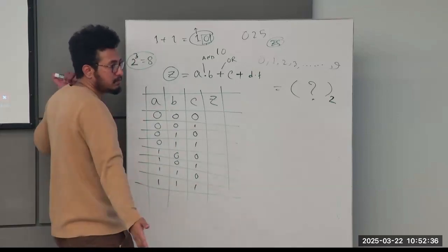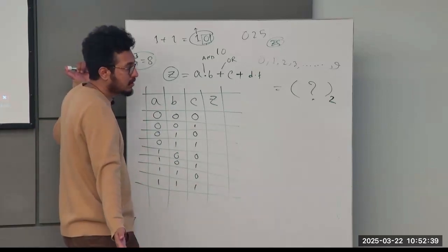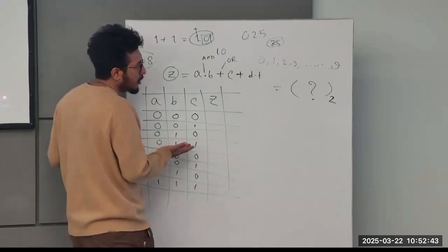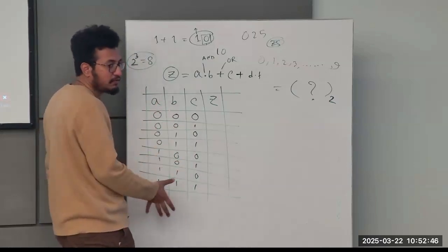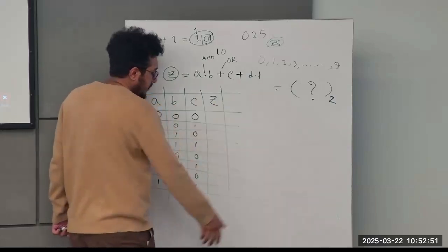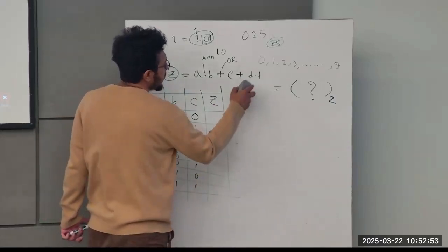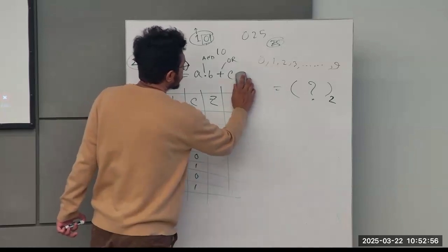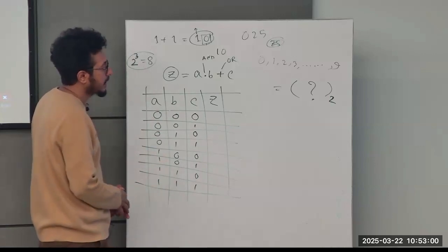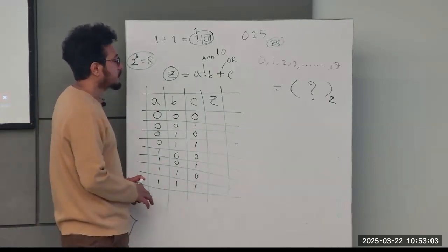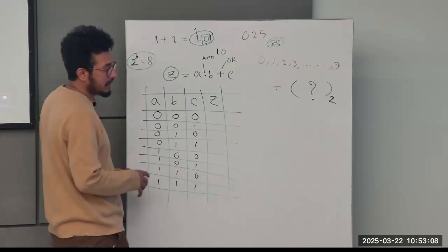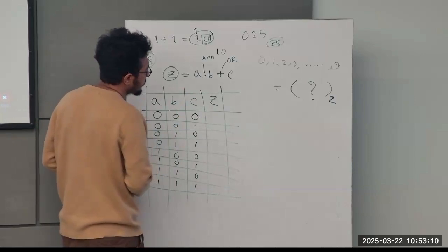your truth table will have 32 rows. You will not miss if you follow these rules: half the number of rows and insert half 0, half 1, half 0, half 1 this way, and divide by 2 again. We move to the next input this way. So go ahead and repeat the video, and you will know that this way you can build the truth table of any Boolean function.